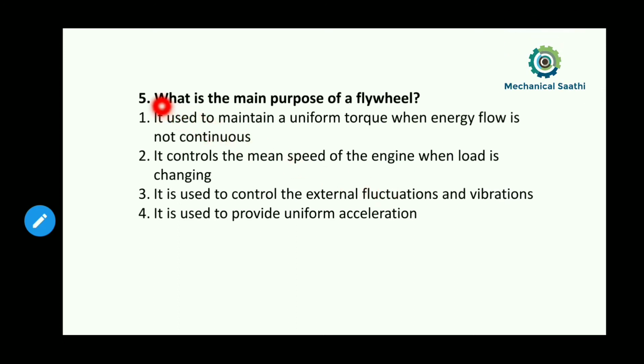What is the main purpose of a flywheel? We know what a flywheel does. Basically a flywheel is used in an engine to get a constant or uniform torque. In the other strokes, excluding the power stroke, we are not getting any power from the engine.